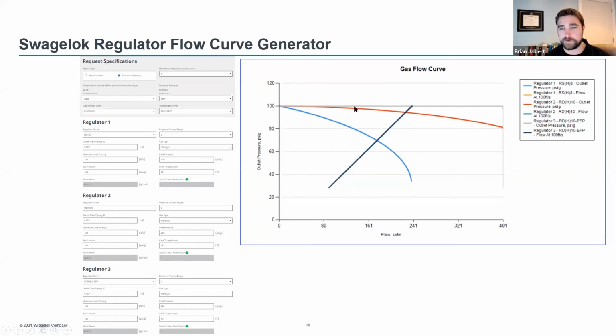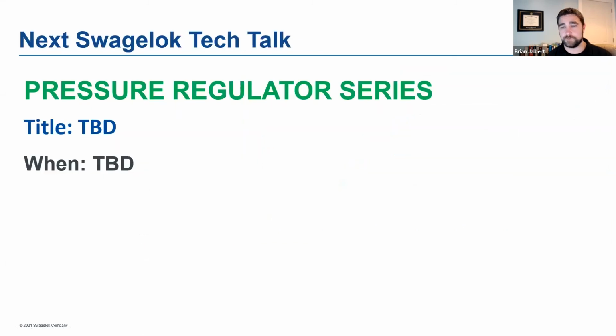And you can't even see the graph for the external feedback option because it looks like a flat line. External feedback to pilot makes regulators extremely accurate and really allows them to utilize pretty much the entire theoretically calculated CV rate that we talked about before. So those are the 2 most common ways that I like to size regulators. The biggest one is the flow curves, most common. And when you get into the larger flow systems, that flow curve generator is an excellent tool.